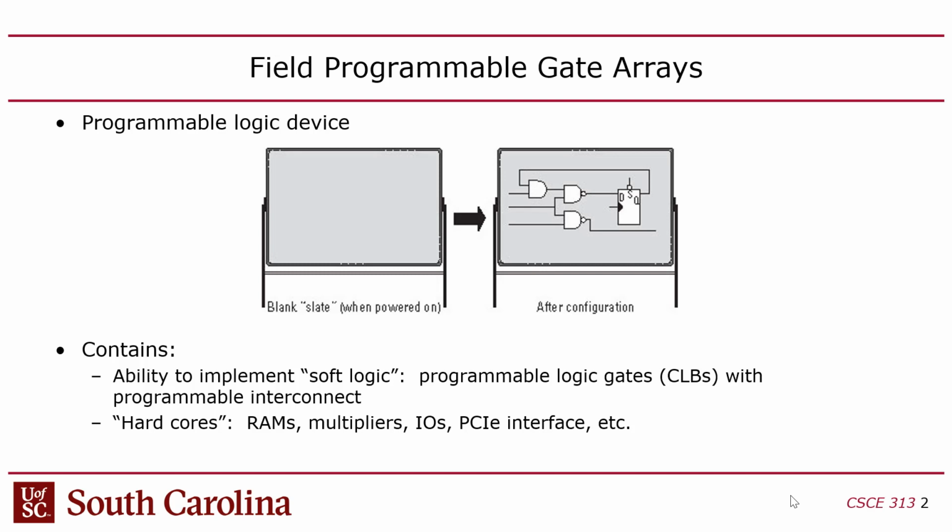Okay, so basically FPGAs allow you to do hardware design without having to fabricate a chip, which takes a long time and is very expensive, as you might imagine. The downside is that you get 10 times less transistors or 10 times less gates than you would if you fabbed a chip, and the clock runs 10 times slower. That's the disadvantage. But if you fab a chip, it costs millions of dollars and takes a long time to get it back, and it's very hard to test, and then generally speaking, the first version of it will never work. I've designed, I don't know, 7 or 8 chips in my life, and none of them worked. We taped them out, they came back, none of them worked.